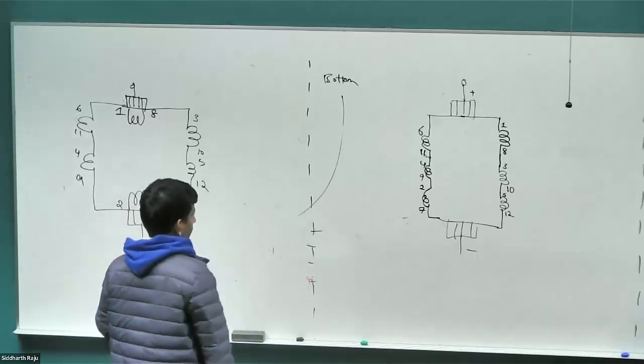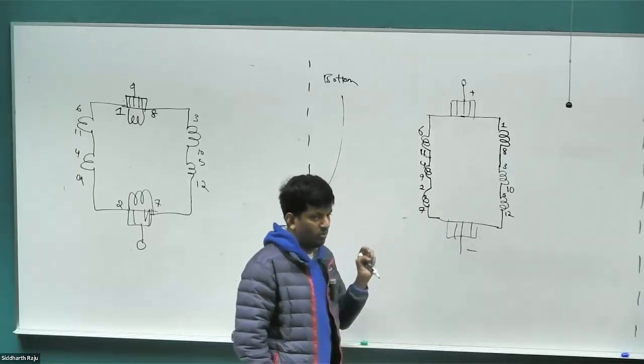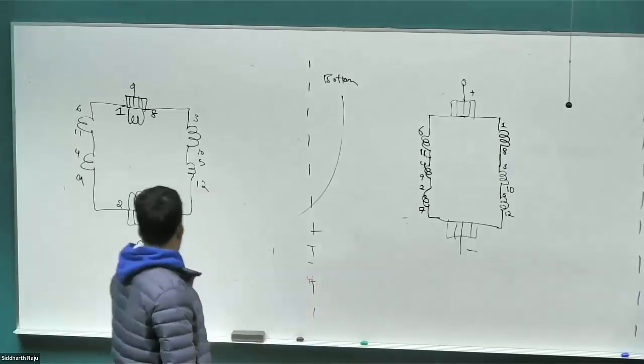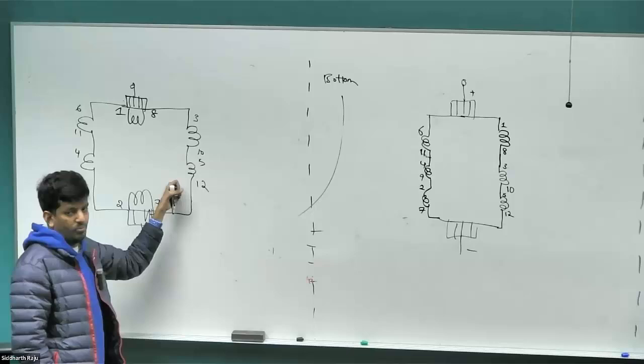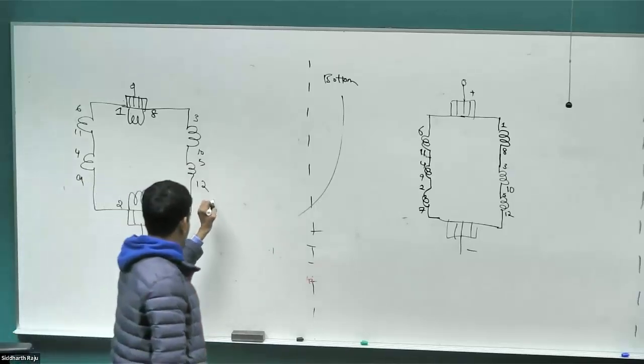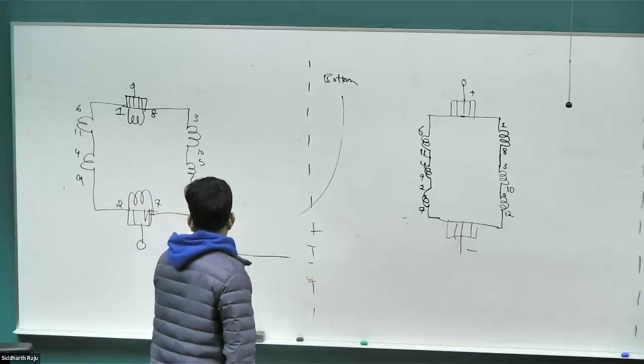So right away you can see previously, this whole bunch of coils, 6 sets of coils, are producing torque and producing EMF. Now these two coils are shorted. But then there are other sets of coils that are still producing EMF. So this was the diagram I drew in the beginning, right? When Thomas asked what the EMF would look like when you have multiple coils.